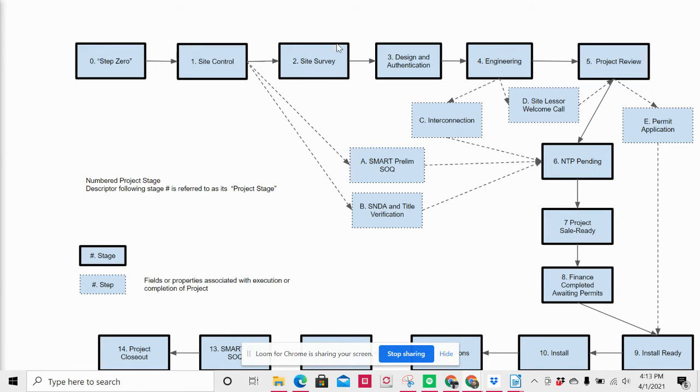So moving on, back to site survey. One of the other things that we are going to have the site surveyor do is take some photographs showing the actual electrical panel, showing the service cable coming down from the weatherhead, and showing the meter on the outside of the house. Now, with a typical residential installation, we would be tying into that, but with this type of process, we're going to be using a standalone meter.